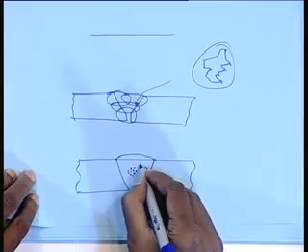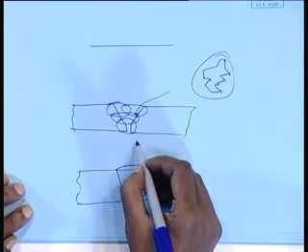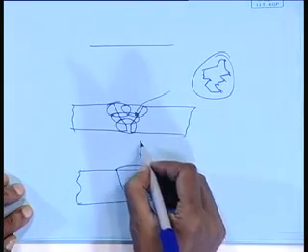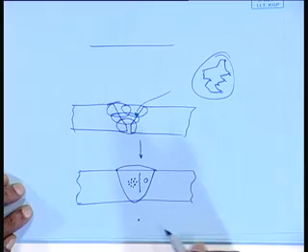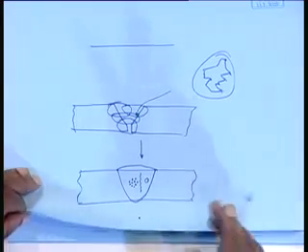Suppose your defect falls in line with the X-ray. Assume a theoretical crack like this, a vertical crack, and your X-rays are coming vertically down, so it will give a spot in the film. You will not realize that there is such a long crack. You will find it's possibly some small defect, a small spot. Though hypothetically it is possible, such a coincidence can be rare.